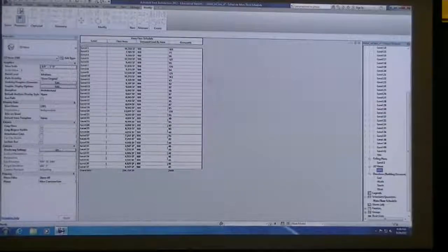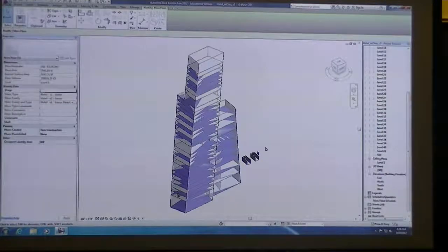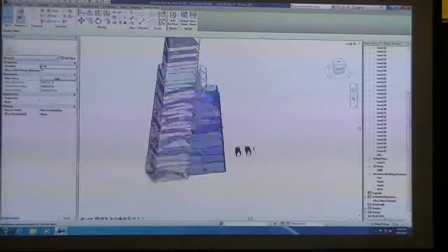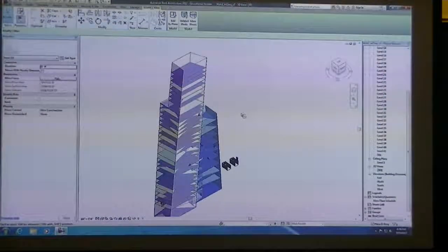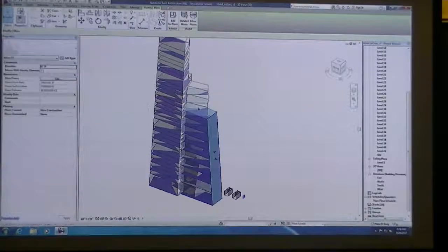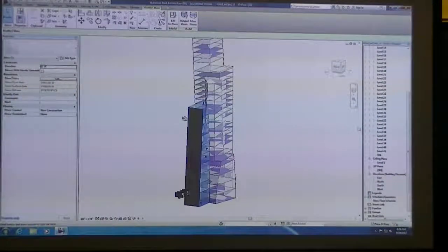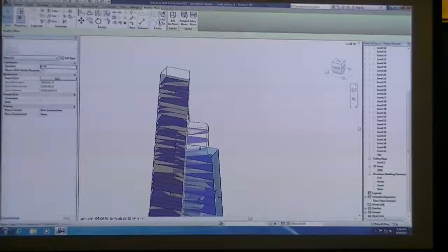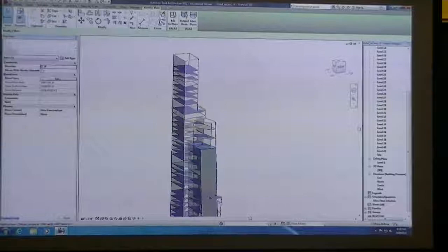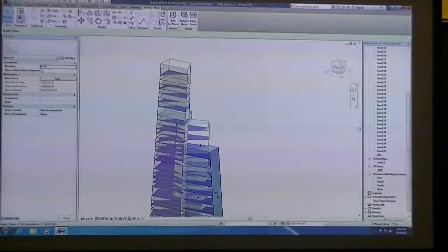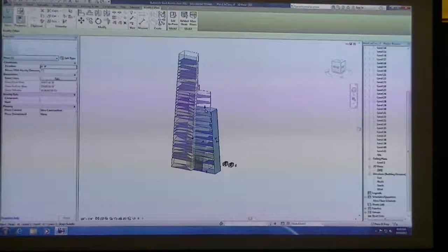So that's a quick exercise to kind of figure out what we need. And you basically need 3 stairs for the whole entire floor. Let's say I've got 3 masses that have 1 floor slab going all the way through the masses. And then when you get up a little bit taller, you can see this tower that's going up a little bit higher. I'm obviously not going to need 3 stairs for this little part. I could assume that I just need 2 means of egress coming out of that location. So don't go too wild with adding in stairs everywhere.